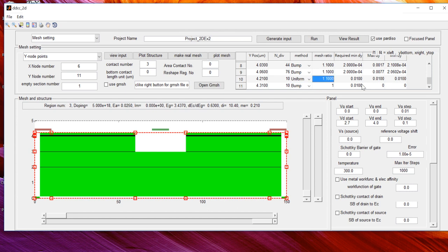If you put 100 nanometers of ITO, your LED will emit nothing because ITO is highly absorbent. ITO is highly absorbent, so usually it's not more than the range of 10 nanometers. ITO for blue is not so bad. Laser is probably bad, but the transparency is still like 90%, so it's not so bad.